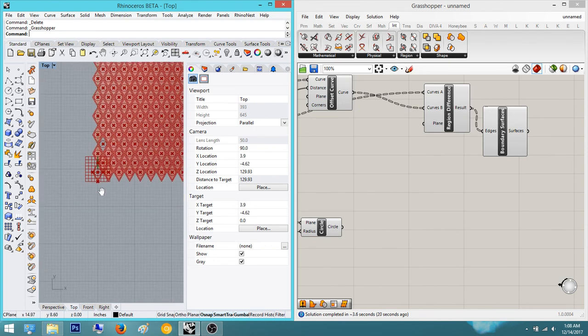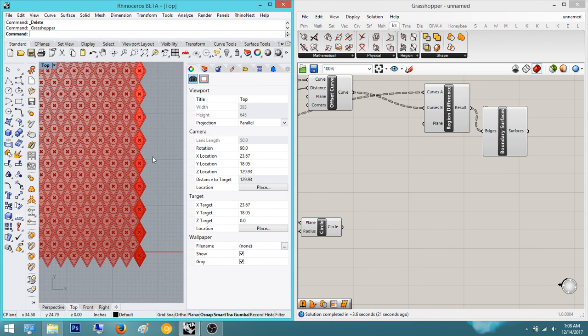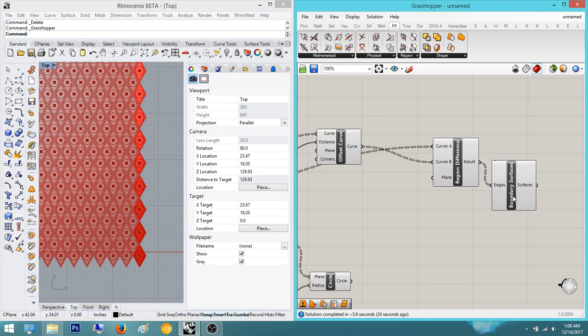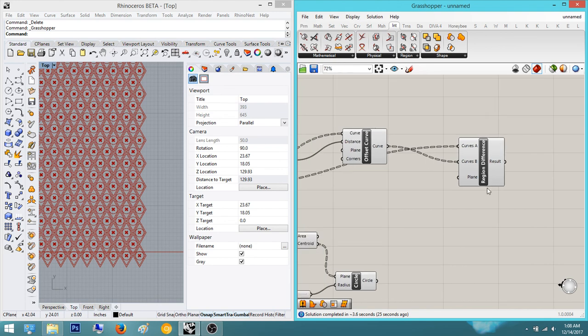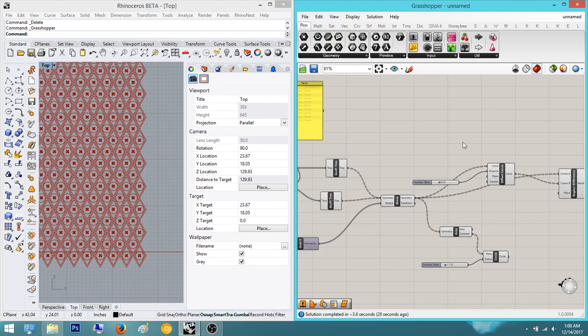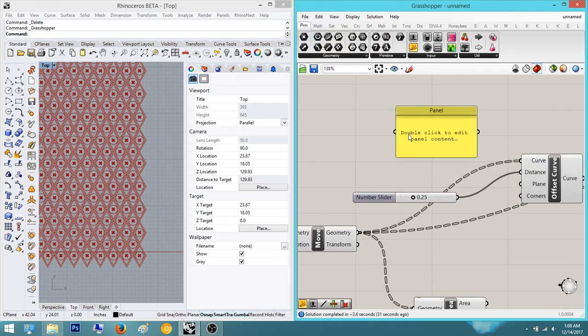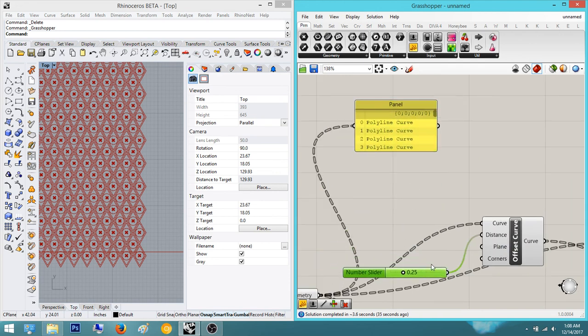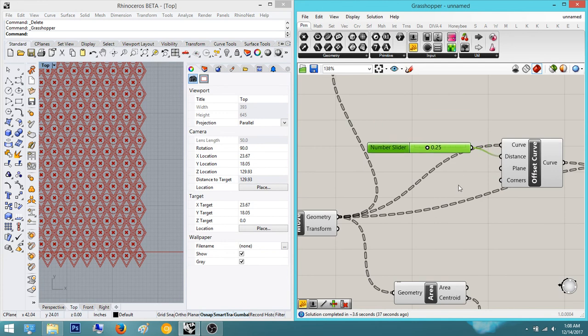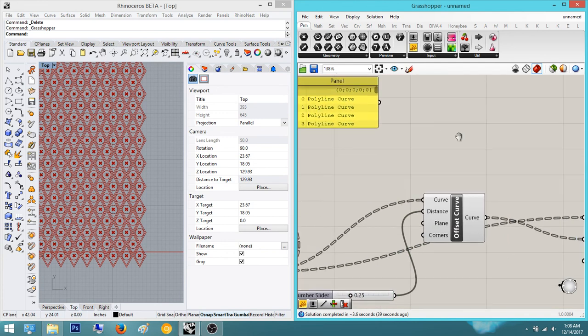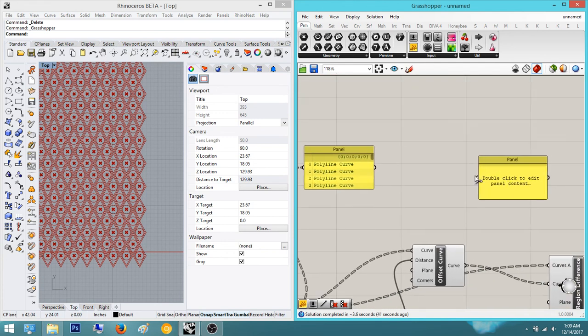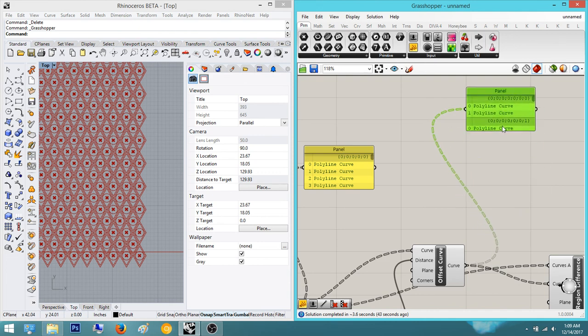You're like, what's going on? Did I mess up something? No. Now this is a listing issue, and I figured out the issue on this when I was making it myself. So let's go throw in some panels. That's the first step if you have a list issue. If something goes wrong, if you logically think about it and like, oh, that should do the boundary surface, and it doesn't, it's almost 100% of the time a listing issue, or you didn't plug something in.